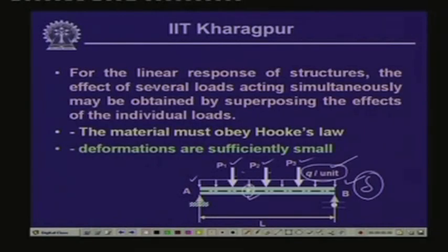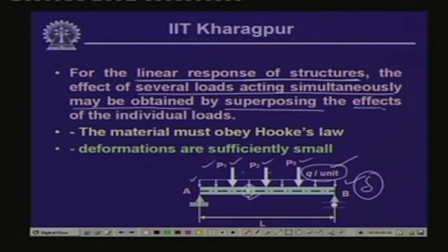And this is what the method of superposition says: for the linear response of the structures, and this is quite important, when the response of the structures is linear, it means that the deflection which we compute is a linear function of the load, and then the effect of several loads acting simultaneously may be obtained by superposing the effects of the individual loads.